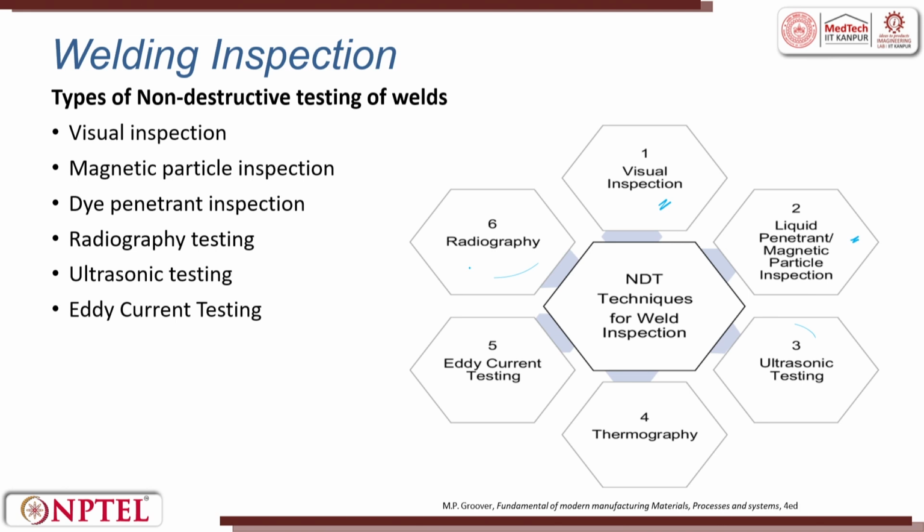Radiography is X-ray taking like we do for humans, and eddy current testing is where we pass current and try to see the response and where the cracks are getting formed. So, I am giving you all the non-destructive methods which are extensively used in welding or in any manufacturing process, so that we can evaluate the joining without damaging it.